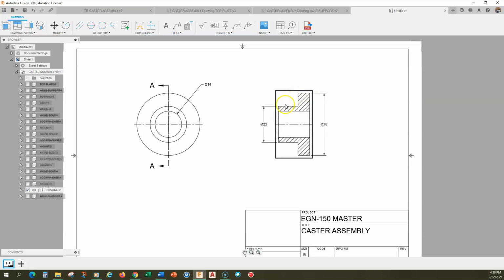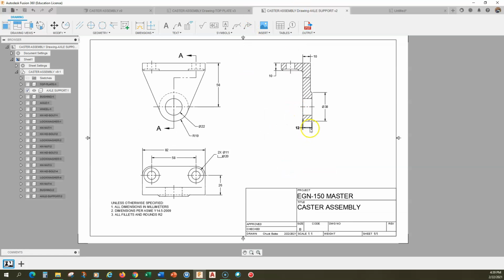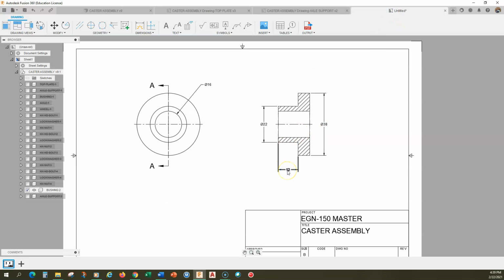Okay. And then cylinders need thicknesses. And here's where we can make sure that we are including mating part dimensions. The thickness of this part right here, and I'll put that dimension in here. The thickness here is derived from or mating with the thickness right there. So mating dimension, we want that thickness. And we probably should also have an overall thickness. Now, what are our options here? Once we determine that the 12 is what we want, what are the other dimensions that we might choose from? Well, we got the 19, and we got this dimension right here, which is the 7.